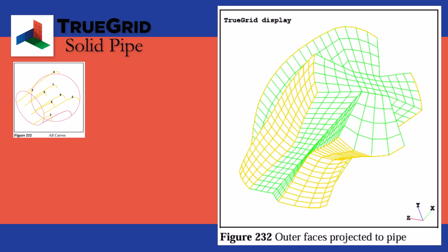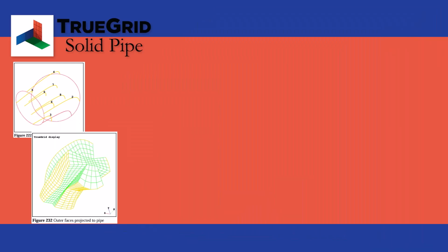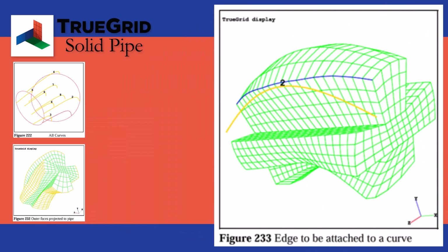The projection method can only deal with a modest amount of curvature between block partitions. When 3D curves which approximate the surface projection are used to initialize the mesh before projection, then this limitation in curvature no longer applies. This will be evident in this example.